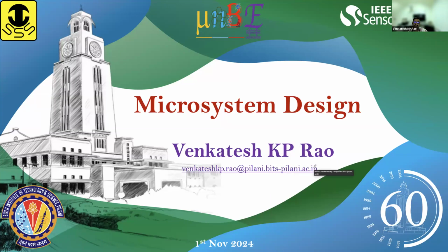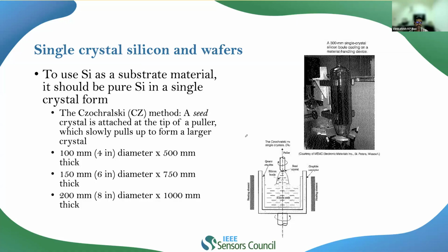The first process is the design of the microsystem under consideration. When we discussed in the previous session, we said one can realize micromachined devices with silicon, polysilicon, or germanium, any of the semiconductors under consideration. Even in the process you will follow for the fabrication of your devices, they are mostly silicon-based sensors. To make any of the silicon devices, the first and fundamental thing is that we need the single crystal silicon wafer. For wafer fabrication, we will go by the CZ method.